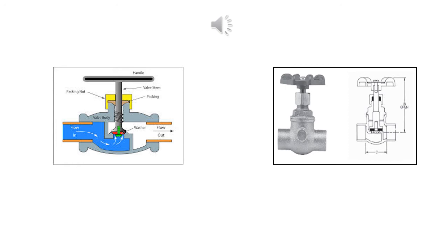Globe valves are used for applications requiring throttling, flow control, and frequent operation. Since the baffle restricts flow, they are not recommended where full unobstructed flow is required. For applications with low temperature, globe valves are normally installed so that the pressure is under the disc. This contributes to easy operation and helps protect the packing.